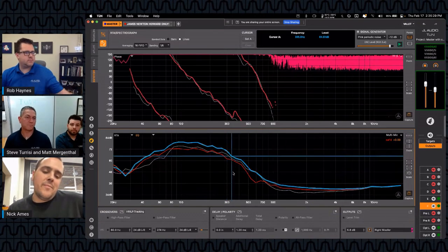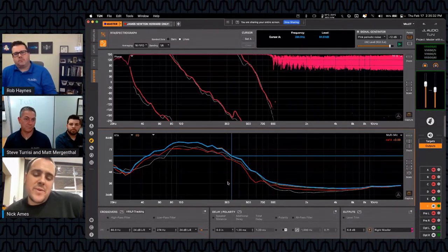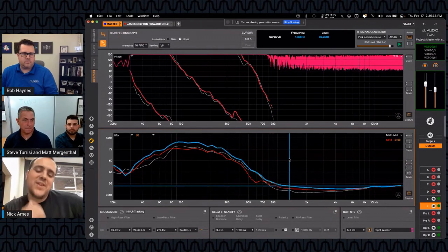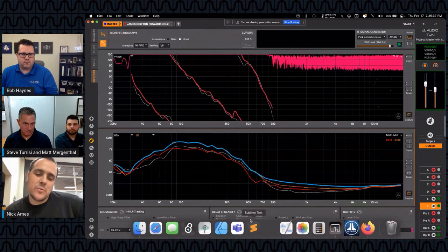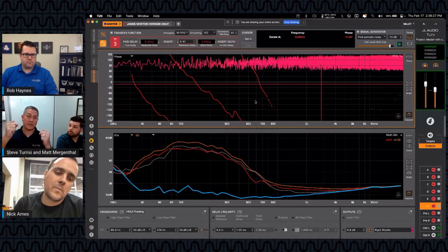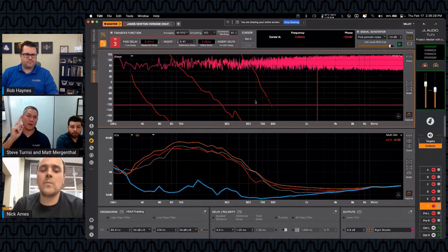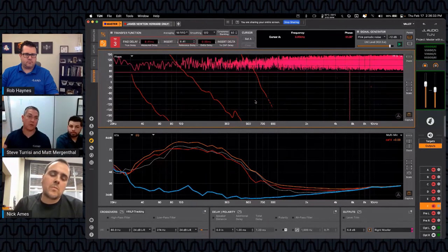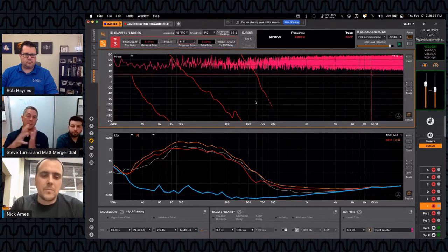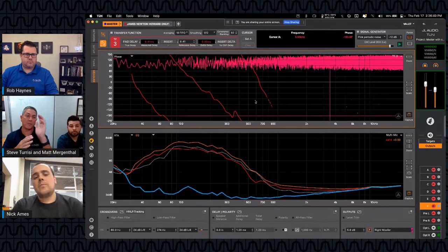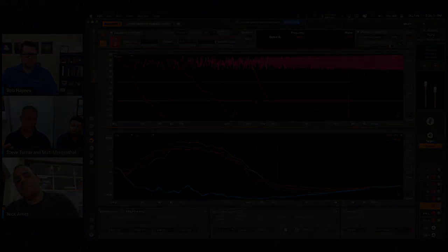Yeah, and the mid bass is going to start handing over to the mid range right at that point. And so anyway, I think that's good right there where it is. I'd probably leave it at 1.20. And when we got them dialed in, then we captured them together as a group because now they're operating as almost like a single channel in terms of the time domain and their response characteristic. So now with these combined mid-bass drivers that are already very well aligned, we're going to try to extend that alignment down to the low frequency where the subwoofer is going to pick up.